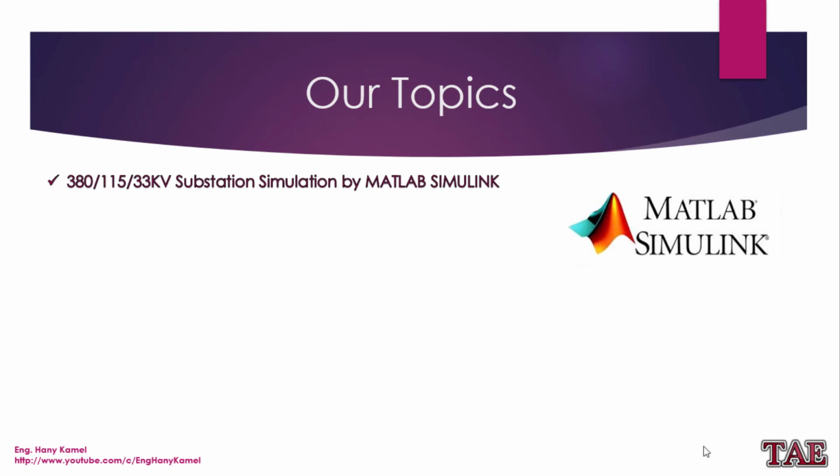So our topics today: we will simulate a 380 over 115 over 33 kV substation by MATLAB Simulink. We will apply the final settings on the 33 kV feeder over current and earth fault protection relay. Already we built this protection relay also in MATLAB Simulink in our simulation.